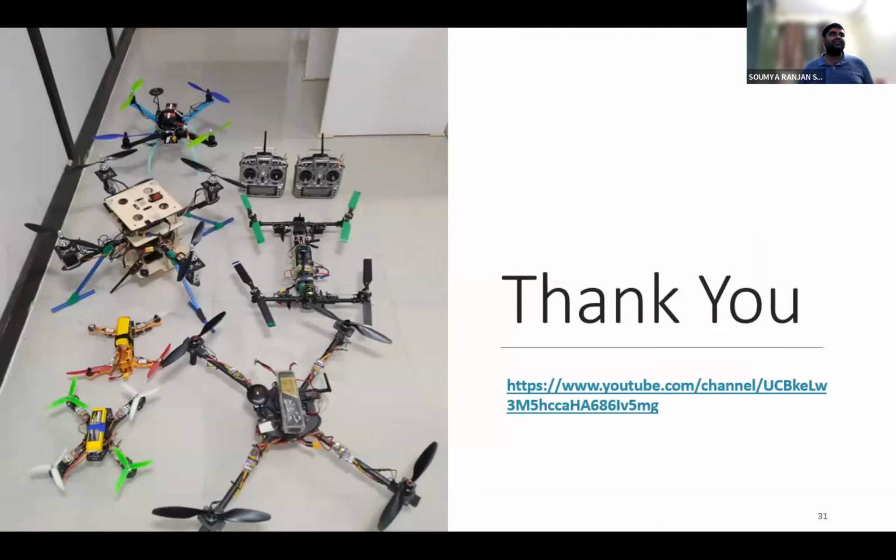These are a few of the quads that we have assembled in our lab, some for practice, and we have also worked on the variable pitch quad rotors. What we are currently aiming at is the variable pitch quad rotor, as Professor Abhishek was also mentioning, which is a single engine driven quad rotor. It is designed for that purpose, where you can change the blade pitch angles. We are trying to see if a tilt quad rotor can be designed so that it is again a single engine based quad rotor, so that with this tilting capability, the position and attitude can be decoupled.